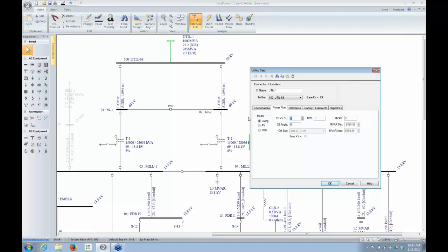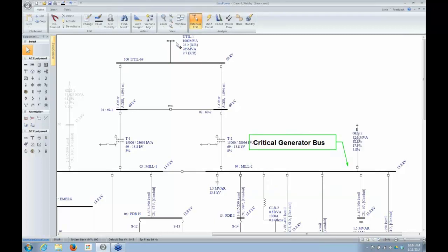Now you may need to create different scenarios to model different PowerFlow conditions. The scenario manager is very valuable for that because we usually have different PowerFlow scenarios we want to model, so we can create different PowerFlow scenarios. But in general, for the swing source, this is going to be, by definition, the voltage that you end up with here. Okay, so just remember you have to have at least one swing source. That's our slush fund for watts and vars. Sometimes it can be negative, sometimes it can be positive, but it has to have a way to balance these out. Okay, so the other typical source you're going to deal with is our generators, synchronous machines.